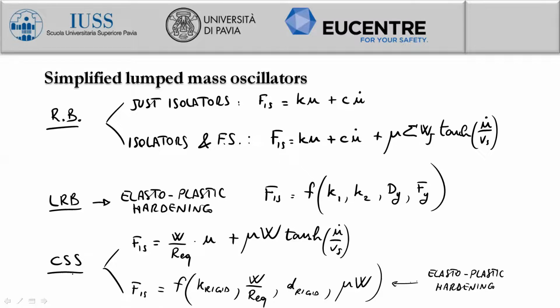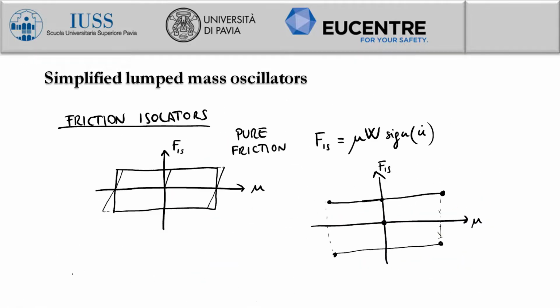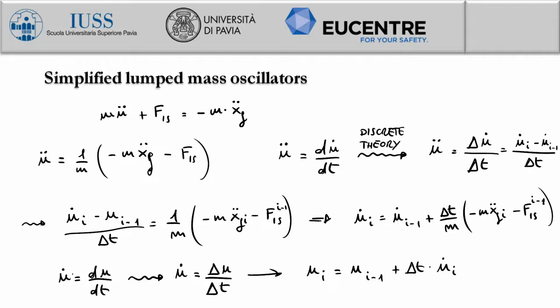Okay, so these are the main rules to actually time integrate the single degree of freedom oscillator. Now we are going to do some numerical simulations within Matlab. And obviously, if you remember in the very first slides, when we discussed the time integration method, you see that here in the second member of the first equation for the computation of the velocity, we have the application of the explicit method.